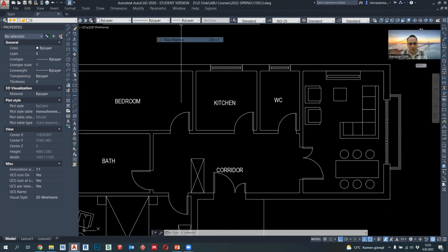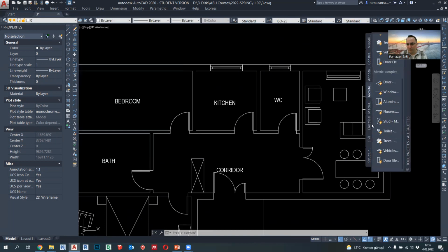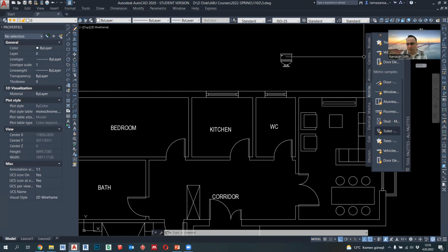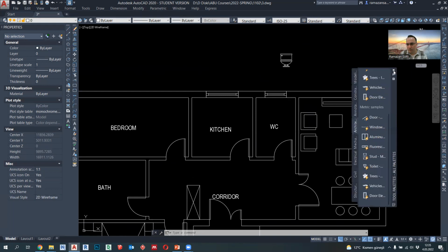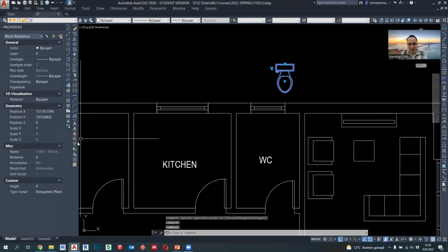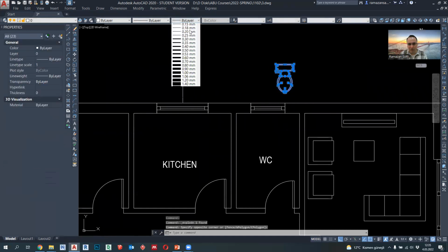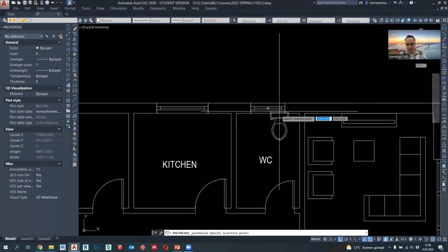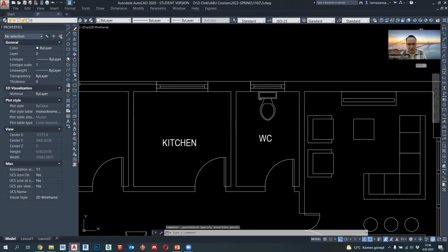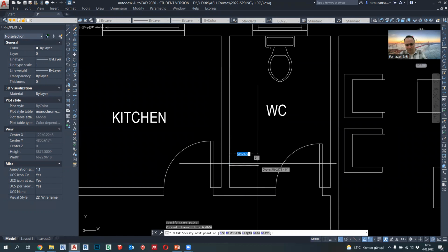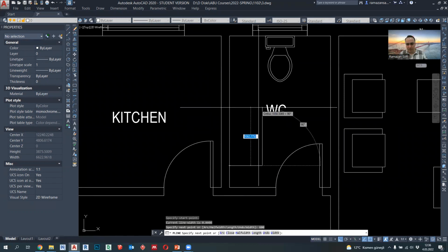Let me show you. Yes, tool palettes. There are ready available components at here, but do not use directly. Always explore, change the line thickness, and then make group again and use. For example, let's locate this here and create a bed, a sink at here, having proper dimension.